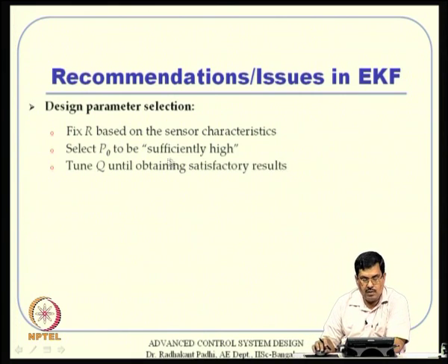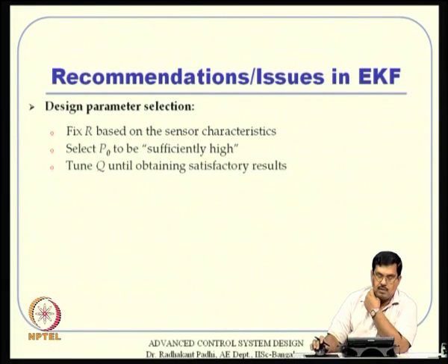What they tell is, first thing is you fix your R matrix, because R is nothing but the sensor covariance matrix. Depending on what type of sensors you have, that will be fixed, because you study the nature of your sensors and then find out the covariance matrix for that, and that is the reality. So, do not try to fiddle with that. Keep your R matrix fixed based on the sensors that you are using.